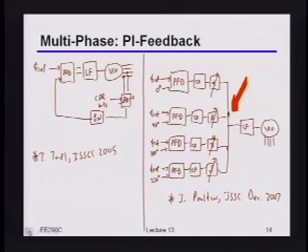Can you do the tap control by changing the current for this? What do you mean, tap control? I mean the alpha, beta, gamma, and delta. Oh, yeah, absolutely. In practice, what you really do is you just adjust the currents in the charge pump, or you may even have some switches and then just have two charge pumps with adjustable currents. Lots of ways you can build this.